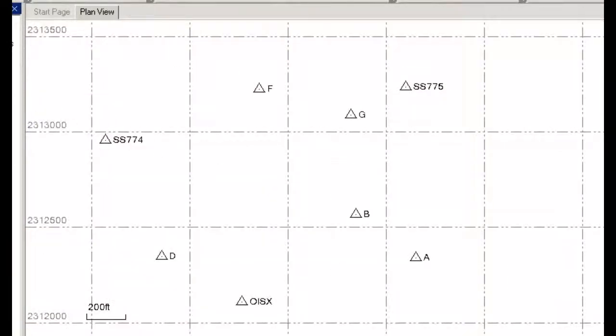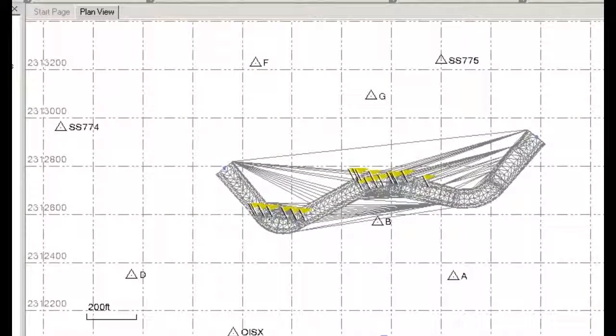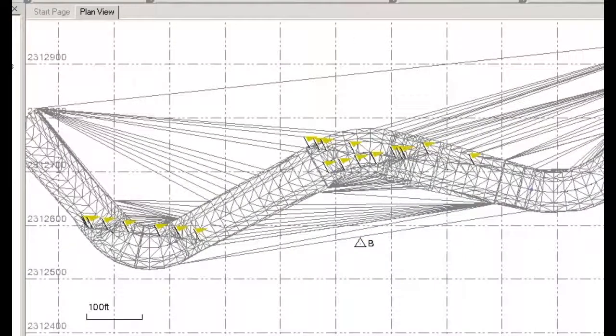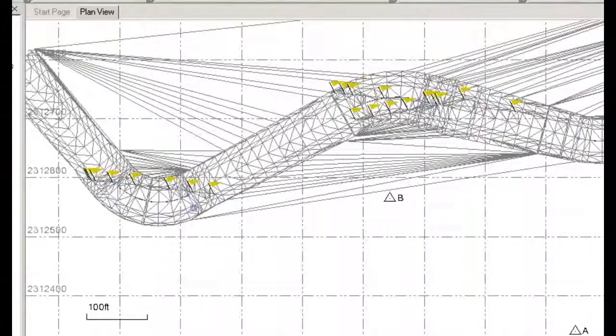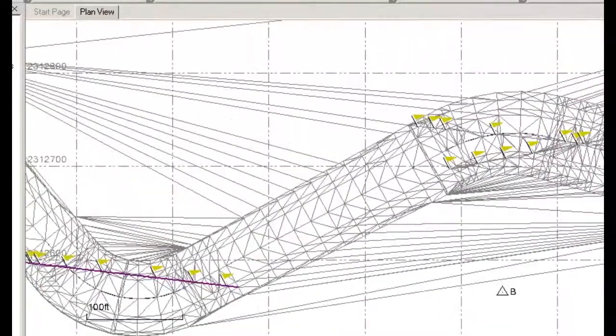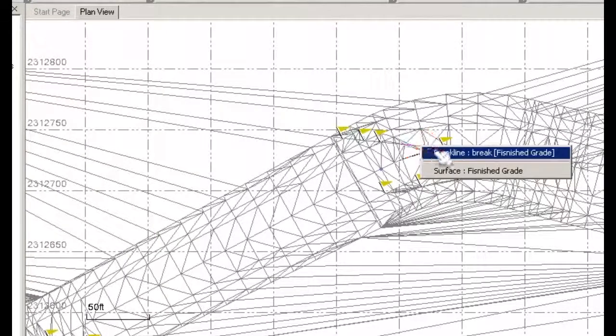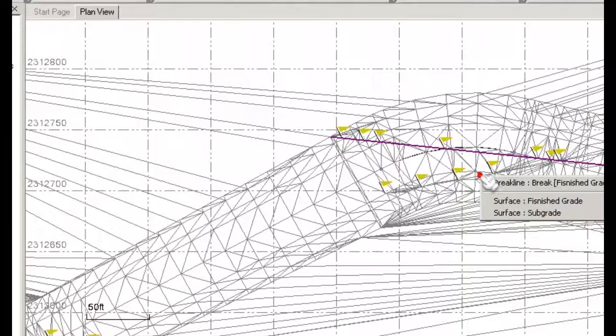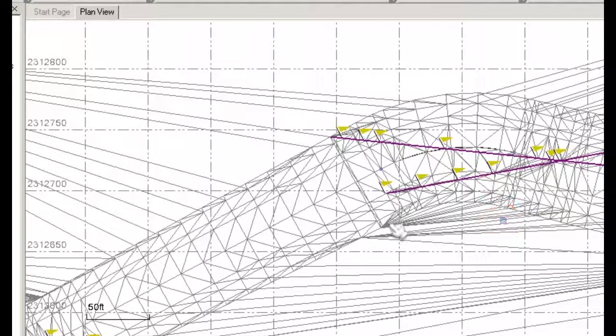And also I have a little road that I can import here. So in this case we see that there are some error flags here. So this is one of the benefits of Business Center, that it flags us errors in the data that we got from the engineer, for instance, but also we have the possibility to fix these problems. So in this case here, we have a couple of break lines which were exported accidentally, and I can now here go ahead and just delete them.